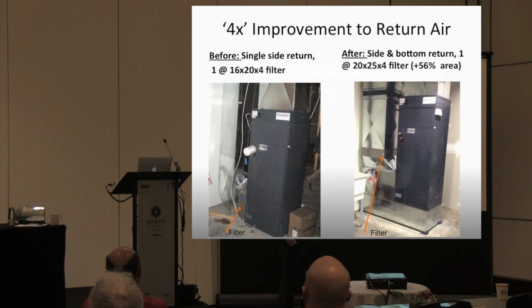Well, this triggers all sorts of vortices. This is where the 50 feet of equivalent length comes from, is we've seriously restricted the airflow by pounding past this one fitting. But that ain't nothing. There's a double, triple whammy in this stupidity. Where do we put the filter? Right here. What happens to the filter? Only the bottom half gets any air through it. What is the velocity of the air going through the filter? Twice the velocity in half the area.